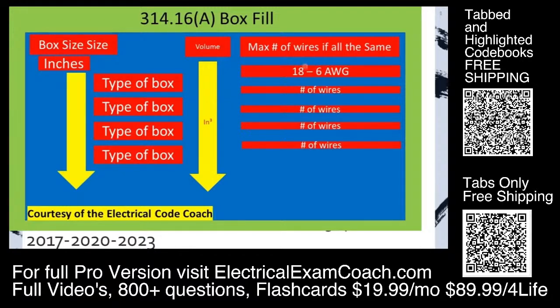Then when we come over here to the far right of the table, it's one of my favorite pieces. It's actually like a cheat sheet. If all of your wires are of the same size, you can use this part of the table and make it very simple on yourself. First thing you'll do is come over and find your gauge of wire. Then you'll come over here and find your type of box, and then come over and tee off with how many wires can fit inside of that box. It's very simple. Now let's look at the second table that we're going to be dealing with for box fill.